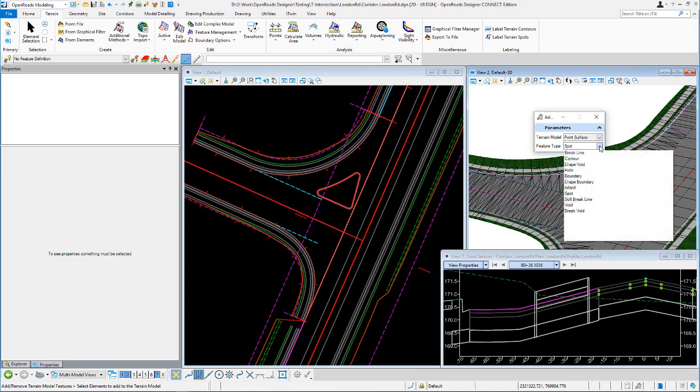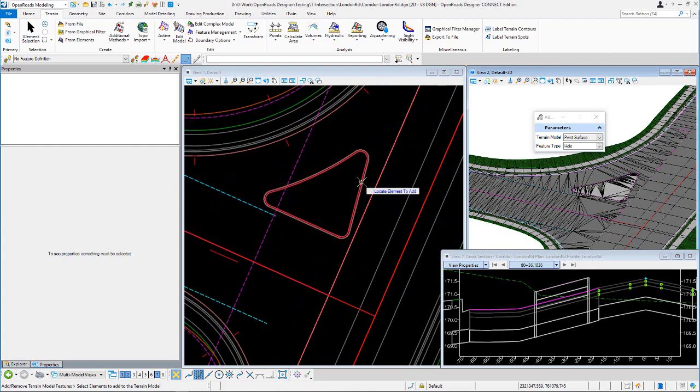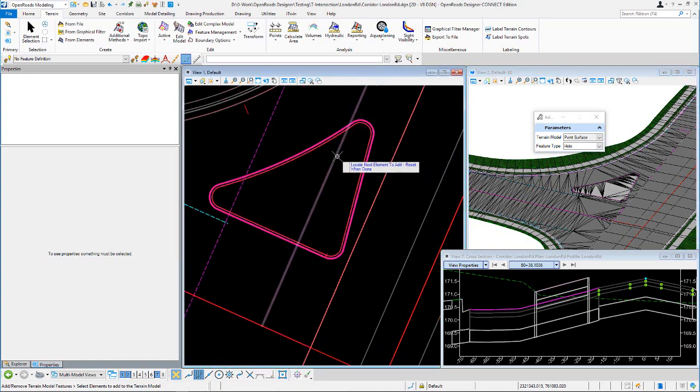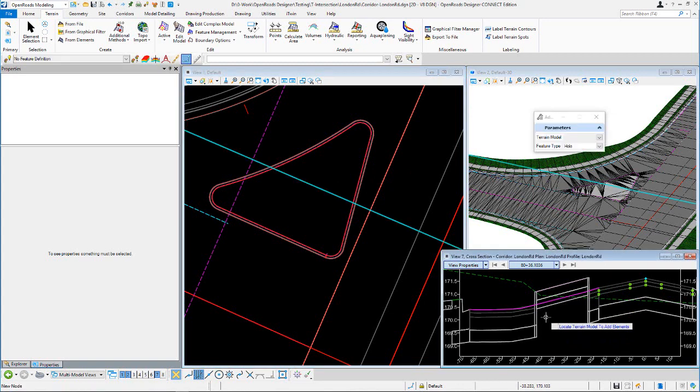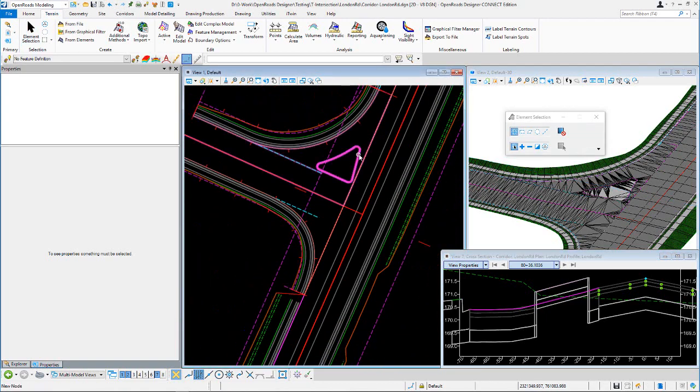And then this is not a spot. I'm going to add a hole there. I'm going to come in and grab not the cell, and right click, not the linear template, but the complex element, that EOP, reset, and confirm that's a hole. And then if we come back and look at our cross-section view, now we've gotten rid of that pavement structure up under that island. All right, so that's pretty much it on the island cell.